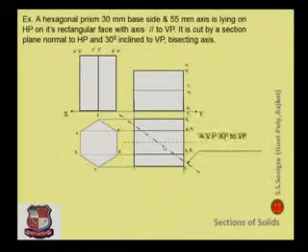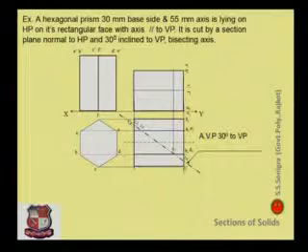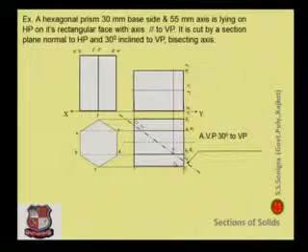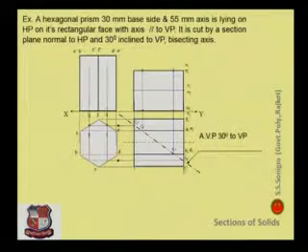Now this is the auxiliary vertical plane, 30° to VP. The cutting plane makes an angle of 30° with the vertical plane. Mark the points. Here 2 points would be there, 1, 2, 3, 4, 5, 6, 7 and 8. So 2 points would be there at each corner. 2 points over here, 2 points over here, 2 over here and 2 over here. Name these points. From these points draw vertical lines like this, 1, 2, 3, and locate appropriate sections in the front